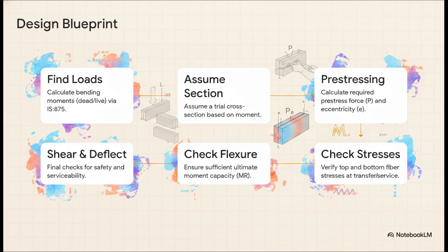Then, and this is a big one, you rigorously check your top and bottom fiber stresses at both the transfer stage and in service. After that, you verify the ultimate flexural strength. And finally, wrap it up with checks for shear and deflection.